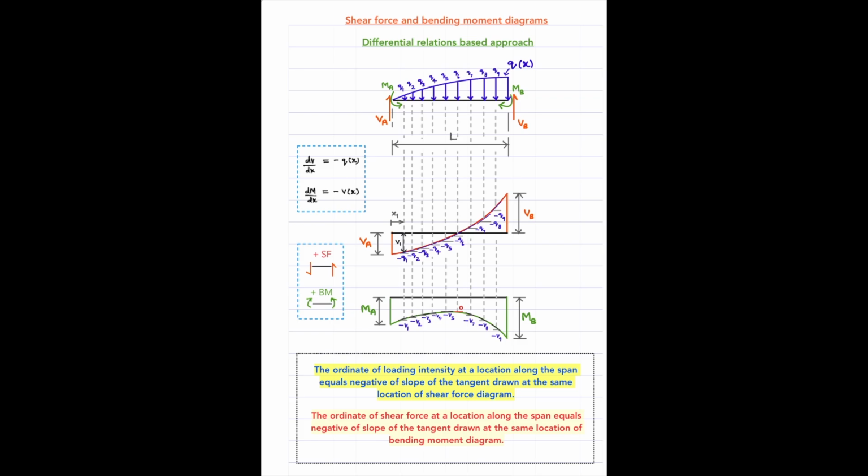Hi, welcome to this new video on drawing shear force and bending moment diagrams based on what approach? Differential relations based approach. In the last video, we derived these two expressions, which are dV/dx equal to minus q of x and dM/dx equal to minus V of x. Based on just these two relations, we'll be able to construct the shear force diagram and bending moment diagram. That's what we're going to see here.